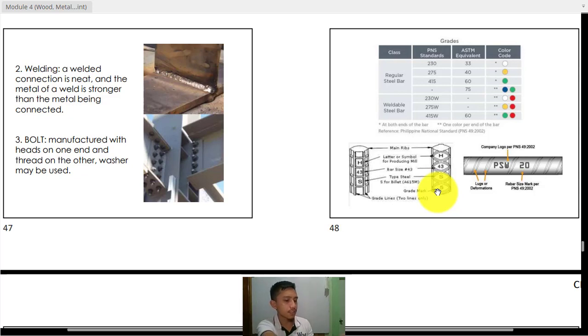Since again, if that is a steel bar with no deformation, it means that is a plain surface, then the connection or the bond between the concrete and the steel is weak against friction. So, let's say this is the steel bar. Before the steel bar reaches its strength, it will fail through friction. Okay, so the concrete and the steel bar will separate without reaching the required strength.